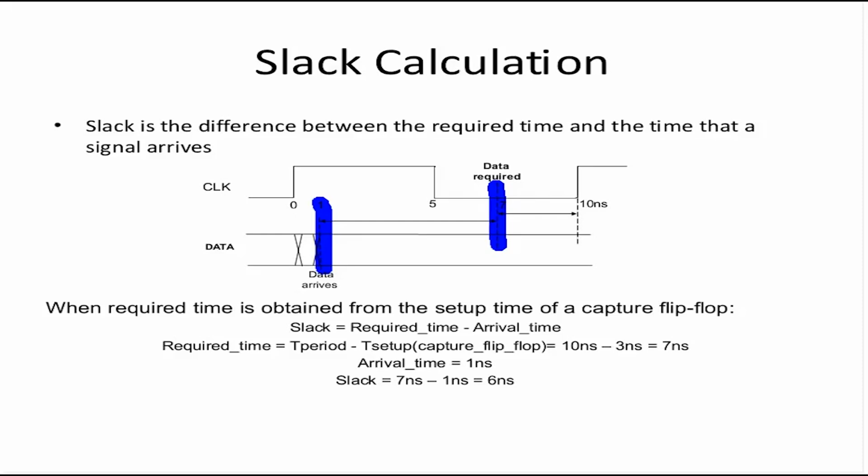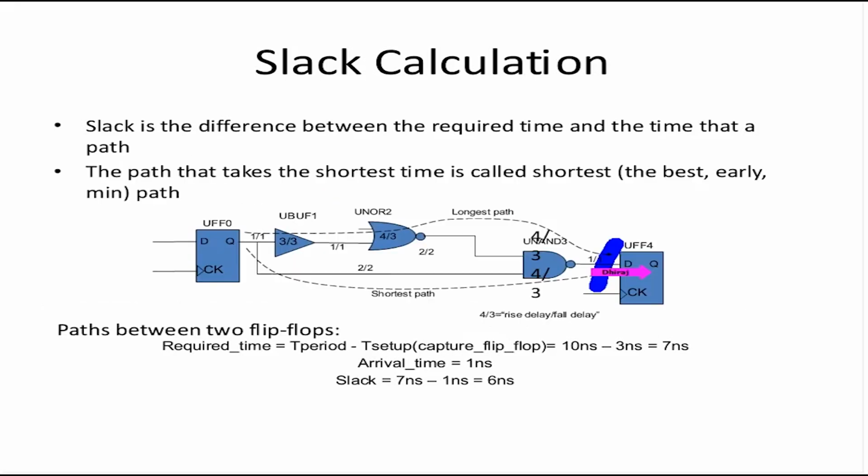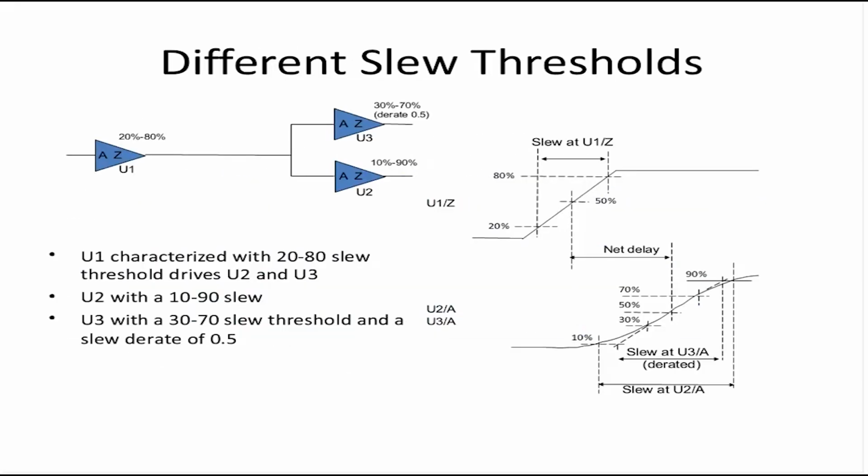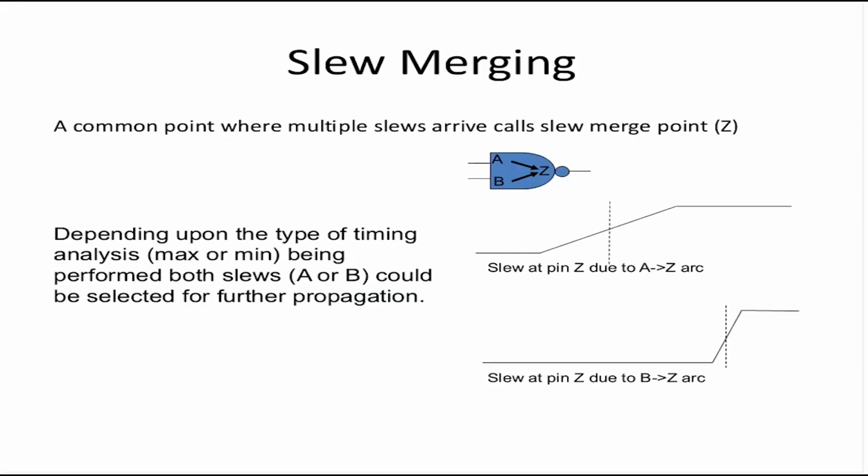And then we know that in case of NLDM, PrimeTime will model the network as a driver model plus the reduced interconnect network model plus the receiver model. The receiver will be modeled as a single effective capacitance called C effective or C total, which will be shown when you do a report timing with the capacitance option. And then we saw that at every node PrimeTime needs to calculate the delay plus the transition value.